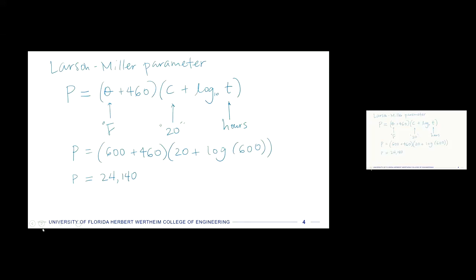So we would expect now, just intuition check, right? If we're at a lower temperature than the test temperature, then this sample should be able to last a lot longer. And if we're at a higher temperature than the test temperature, it should last a shorter amount of time, right? If it's a time, temperature, superposition type thing. Okay.